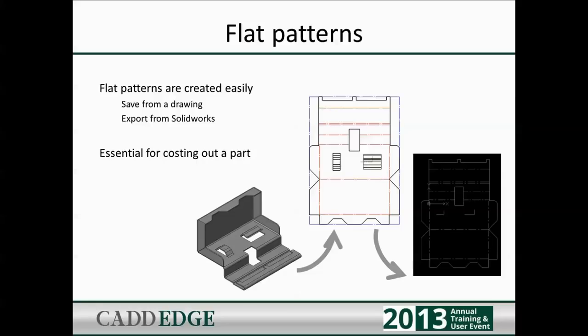And usually if we do that, we save it as a DXF and then bring it into our nesting software or whatever else we're using. So I say they're essential for costing out a part because you get the actual flat size. And if you're adding scrap onto there, you typically need to know what that flat pattern length would be.